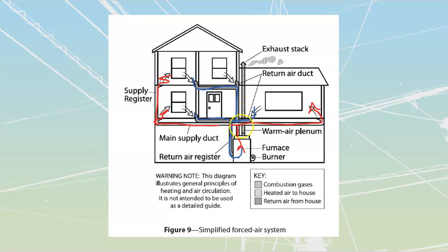Put them up there, put them up there, etc. So we are always going to have supply ducts that are going to be pushing it out. Once again, the supply ducts, even though they are pushed by the furnace fan that's going to be down inside of there, you do want to place them on areas of heat loss up against those walls so that anything these are pushing up is going to get counteracted by any cold air falling down, and we're going to get better mixing throughout our rooms once again.